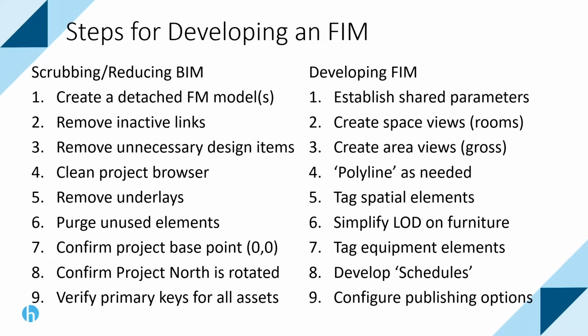Clean up the project browser to orient it more around facilities management rather than construction. Remove any underlays, purge all these unused elements that make the file too big. And then you have things like confirming the project base point is set to 0, 0, confirming the project north is rotated in the direction that you want to publish to Archibus or your FM system, and verify that any data that you want to pull into your database has a primary key that you can use to pull the data in and create the records in the database. So those are things that you want to do to any model that you get, just to clean it up and make it ready for operations.